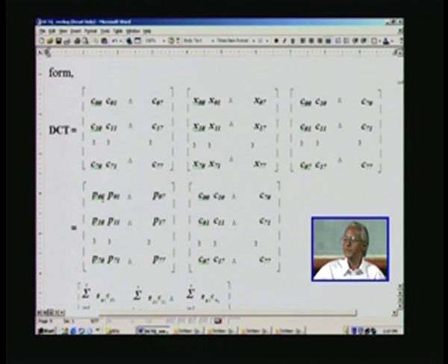And once it is done, we repeat the same thing, retain the same row but change the column now, second column, and get P01, and so on for 8 clock cycles. You would have got the entire row of this, and we term this a partial product here. And once this row is complete, we can start multiplying the second one. So we repeat the same multiplication here.